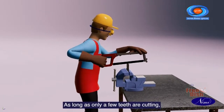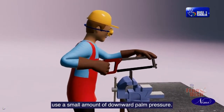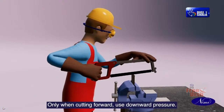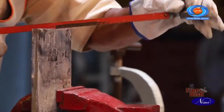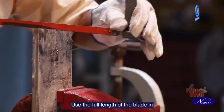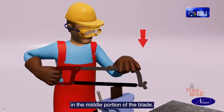As long as only a few teeth are cutting, use a small amount of downward palm pressure. Only when cutting forward, use downward pressure. Use the full length of the blade in order to avoid early dulling of the teeth in the middle portion of the blade.